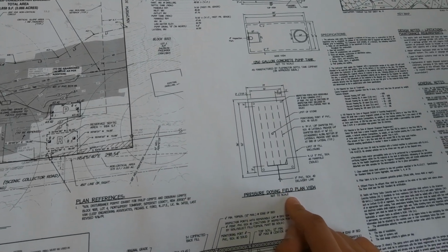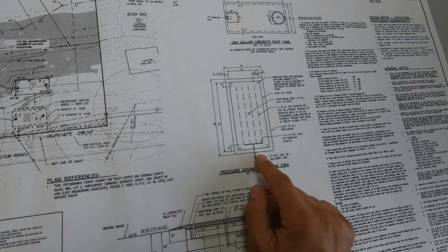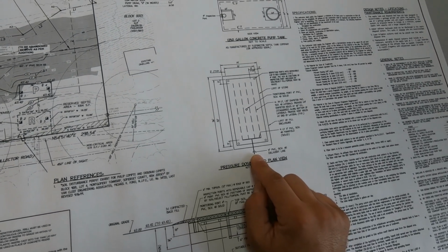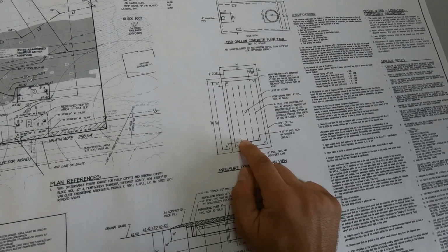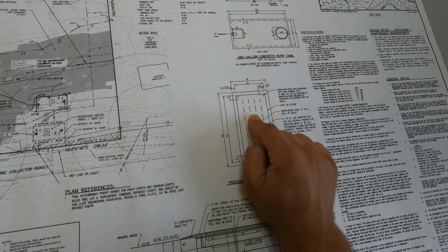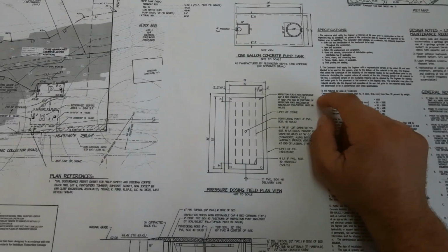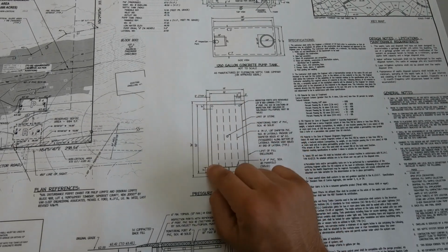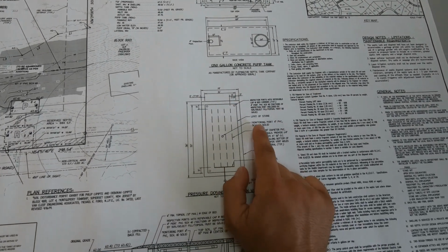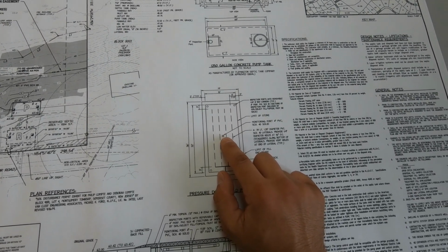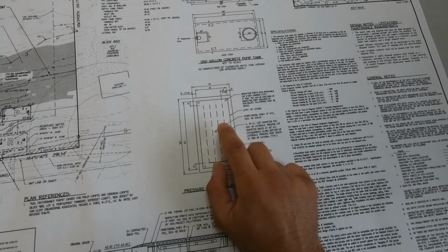All right, and this is your field detail. All right, so this details how the field should look. Again, for this particular job, the delivery line comes here. There's a manifold that goes across, and then there's 4 laterals that extend the length of the field. Now you'll notice here too that there's 4 monitoring ports or 4 inspection ports on each corner, right? 1 on each corner. And there's also a deep inspection port. Now this is sometimes in the middle. Oftentimes the contractor will move this to one side or the other.